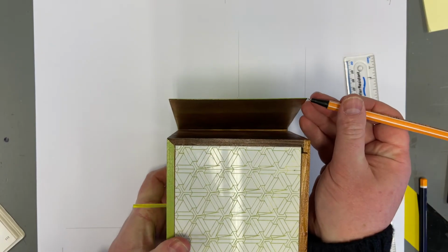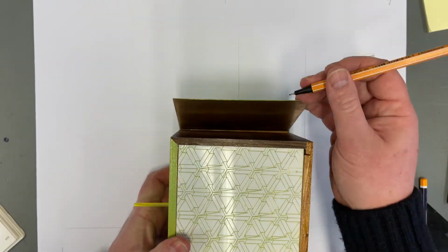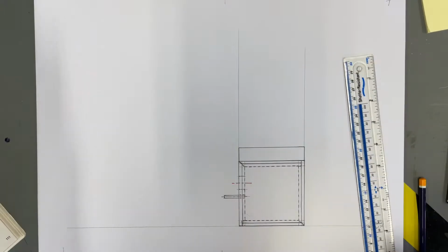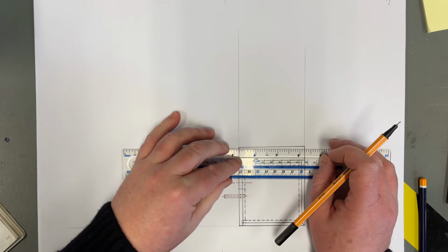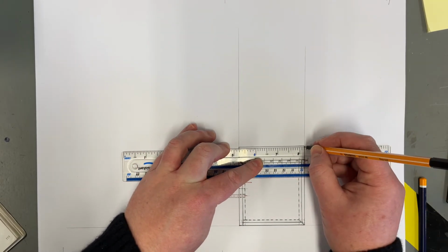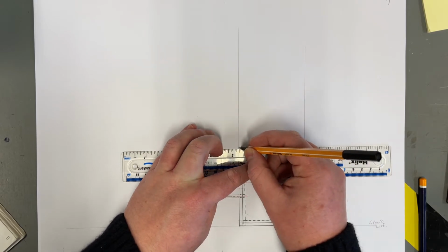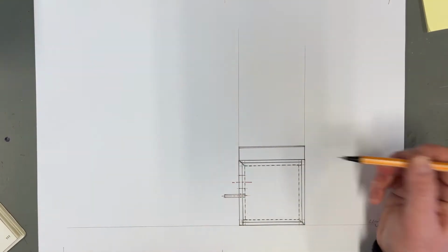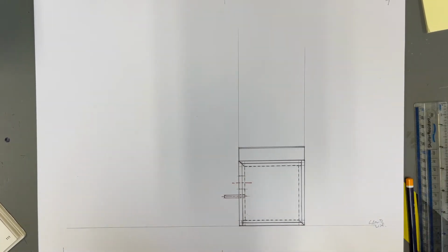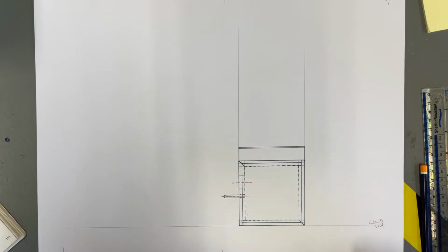Okay, now in this instance, if we look at it, the metal does have a thickness, and we do see that edge of metal from here. So that's not going to appear as a single line. It is only 1 millimeter thick, but we're just going to exaggerate that a little bit on the drawing and just double that line up at the top, just so that we understand that that does have a thickness at the top of that material.